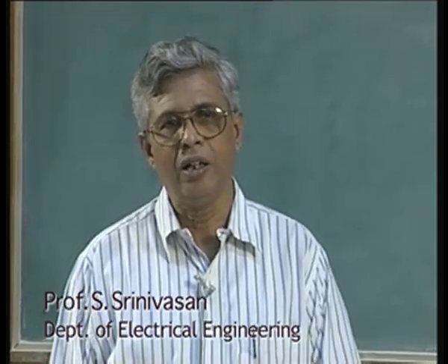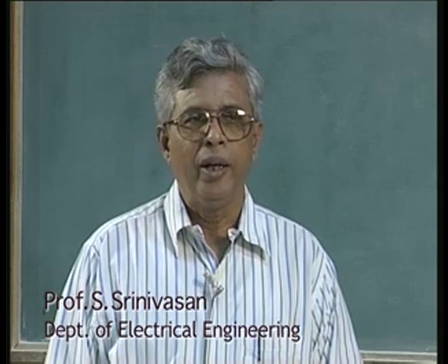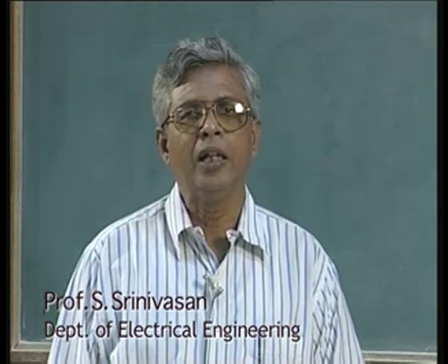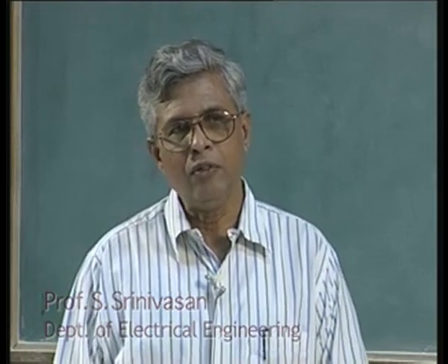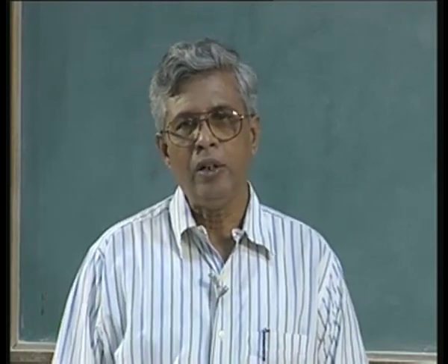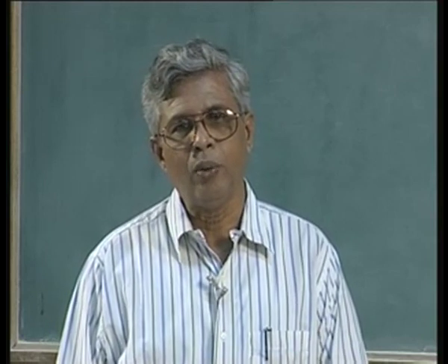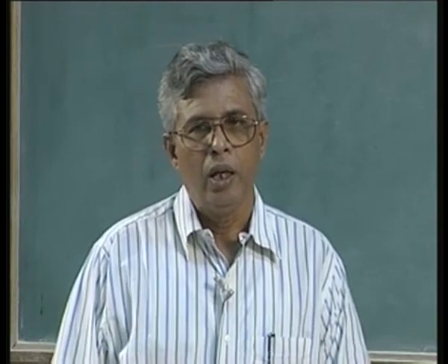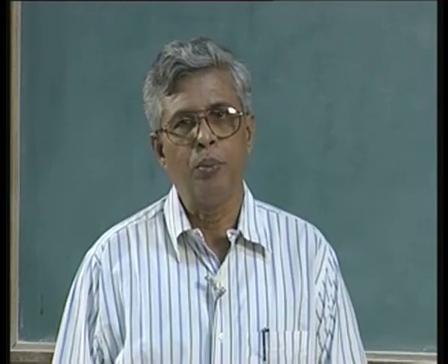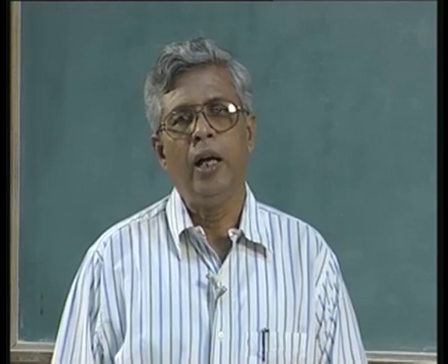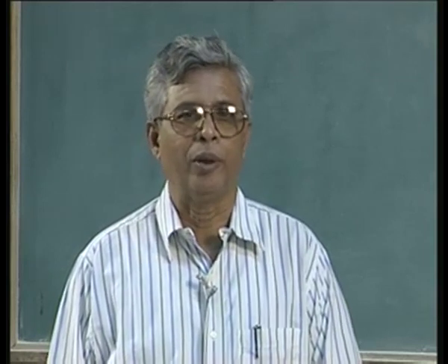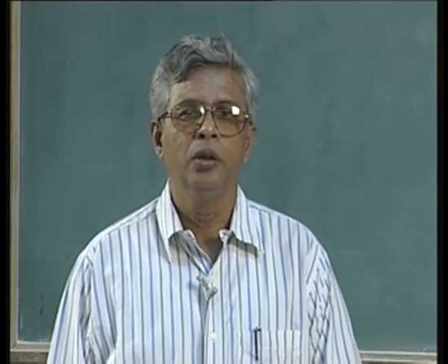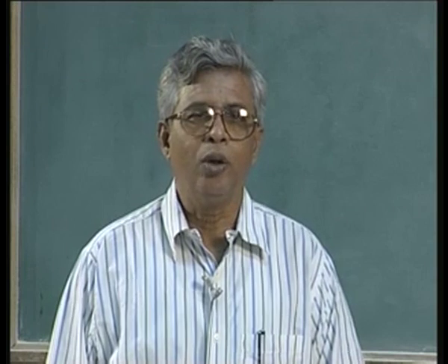So, how do I tailor or reduce my input output specification to the type of multiplexers available on the chip? This we will see from an example. I will give you a function which will require normally 8 to 1 multiplexers, 3 inputs and 1 output, and I am further told that I can only use 2 to 1 multiplexers, 2 inputs and 1 output, with of course no restriction on the number.